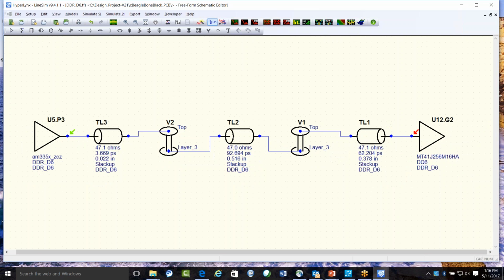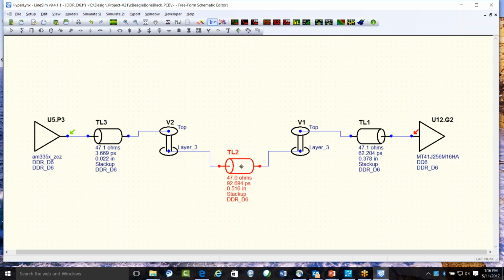And if I had an issue and I thought I knew how to fix it, I could make the adjustment here and prove to myself we found the fix. And maybe that's changing the length of the traces or something like that. Maybe something with the impedance, whatever it happens to be. Okay, and then we would open up our DxDesigner or our PADS layout, make that fix wherever it needs to be made, and then fix the board.